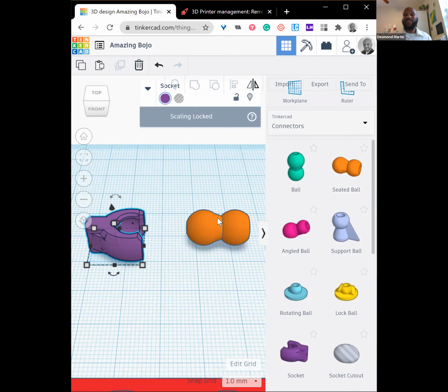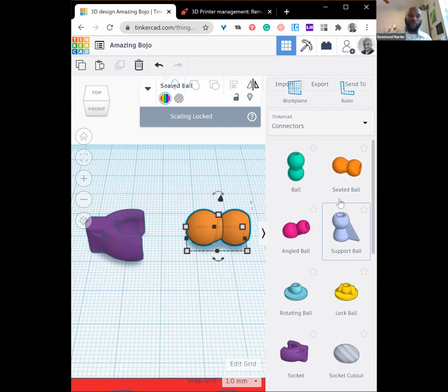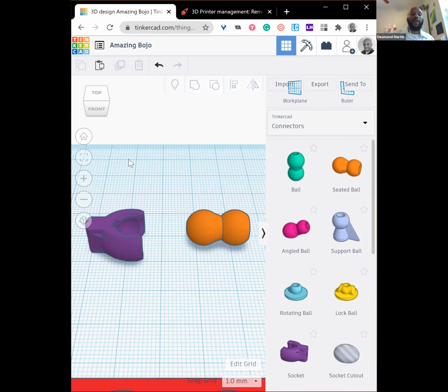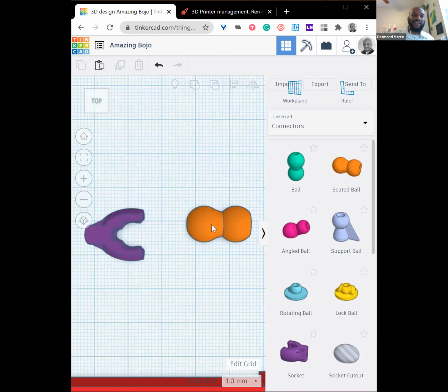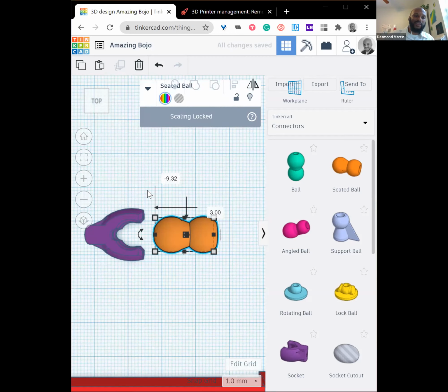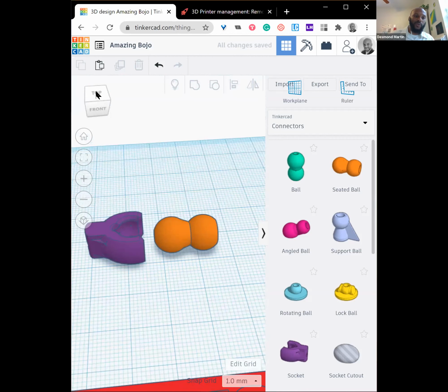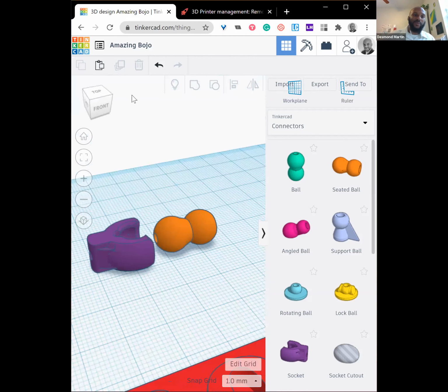What will happen in the way that I can adjust the size of how these parts work is when I get into the slicer, I can scale everything up and scale everything down. That's something that we'll be able to talk about in just a few minutes. But these socketed, these jointed portions are locked in. They're designed to fit in with each other. So the best idea is to take these parts and print them separately. Make sure that there's some amount of space in between them so that when they print, we can remove the supports and they'll snap right into each other.